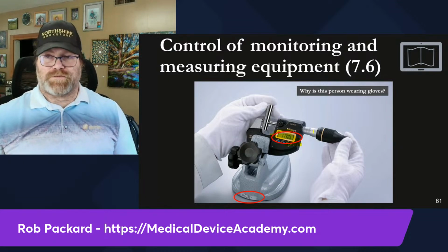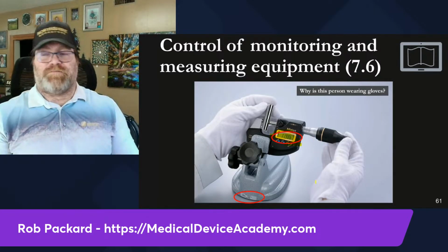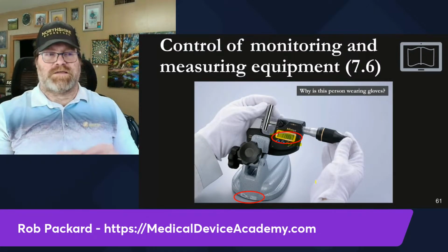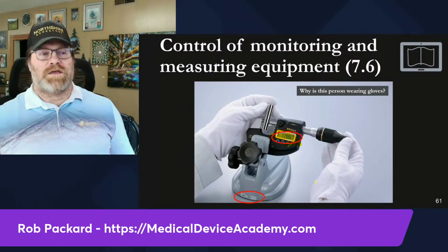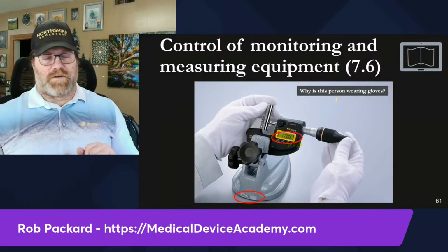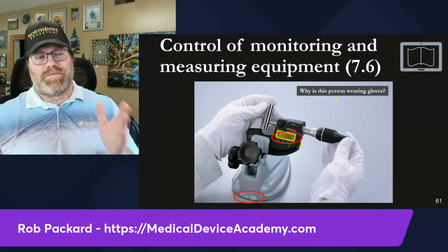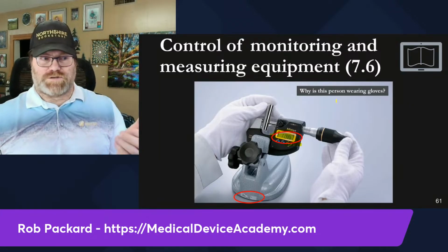But if you have very precise measurements of 2 things like a catheter fitting inside another device, that has a very tight requirement in terms of tolerances. So you might need a 3rd digit or maybe even a 4th. Very, very rare. Probably this is a bench mic being used to verify the accuracy of the calibrated gauge, the gauge pin.